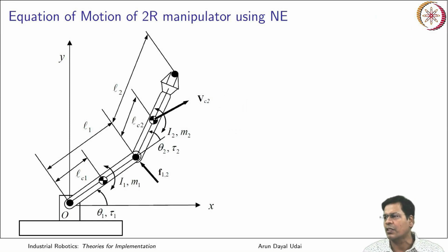We have been dealing with it for a long time, even with forward kinematics and inverse kinematics. This is one which is very, very important, you know already. But in dynamics, if it is planar, it becomes very, very simple. Because the recursive Newton-Euler approach, or the Newton-Euler approach in general, involves plenty of equations, it is normally done comfortably using programming, but to do it analytically on pen and paper is very difficult. So to demonstrate the basic principle, I am proceeding with the 2R planar manipulator only, so that we can handle the equations very well.